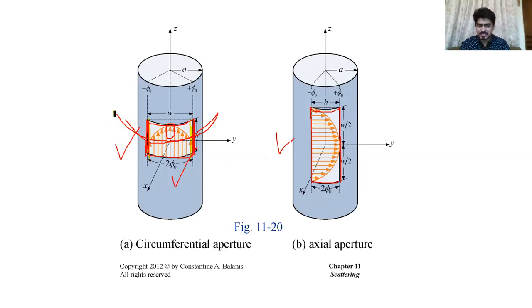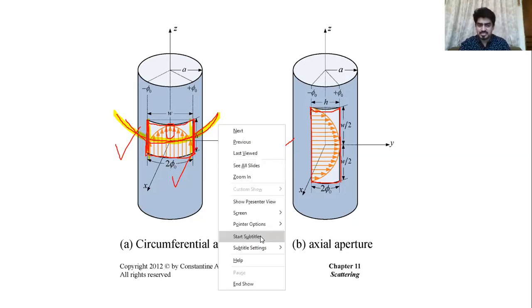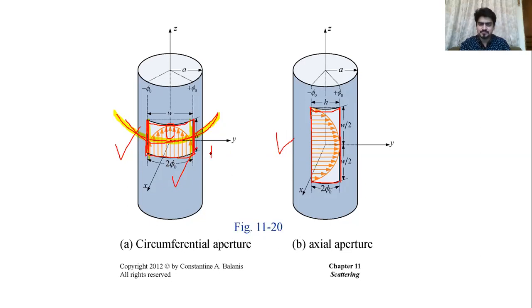So along this horizontal plane or circumferential plane, if you look at this E vector, it is parallel to the XZ plane. So the XZ plane is going to be your E plane, and this XY plane, which is orthogonal to that, is nothing but the H plane: horizontal plane, circumferential plane or azimuthal plane. In that plane, you don't have that much diffraction from the edges.